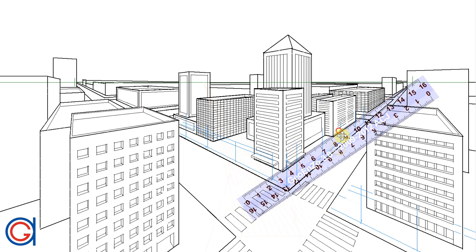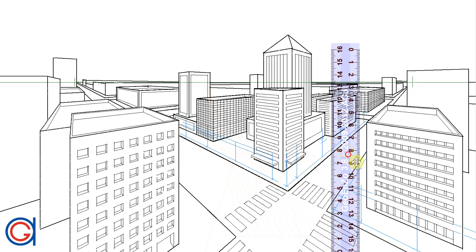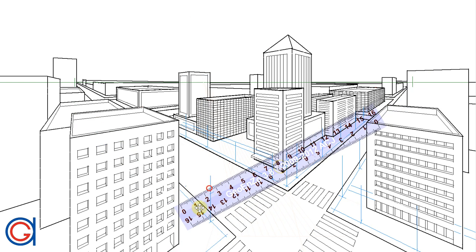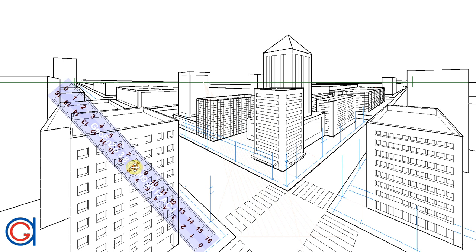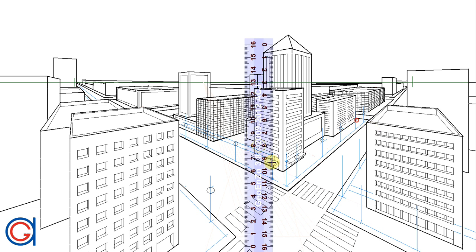So now we are going to continue drawing the street lights on the other street using the same process, except we use the right vanishing point in this case. We are going to use the previously drawn parallel lines to establish the height of the street lights of the second street, as can be seen here. And the next step is to draw the circular lamps at the top of each lamppost. And finally, we are going to draw the lampposts closest to the viewer with a double line, as we can see them better and in more detail.